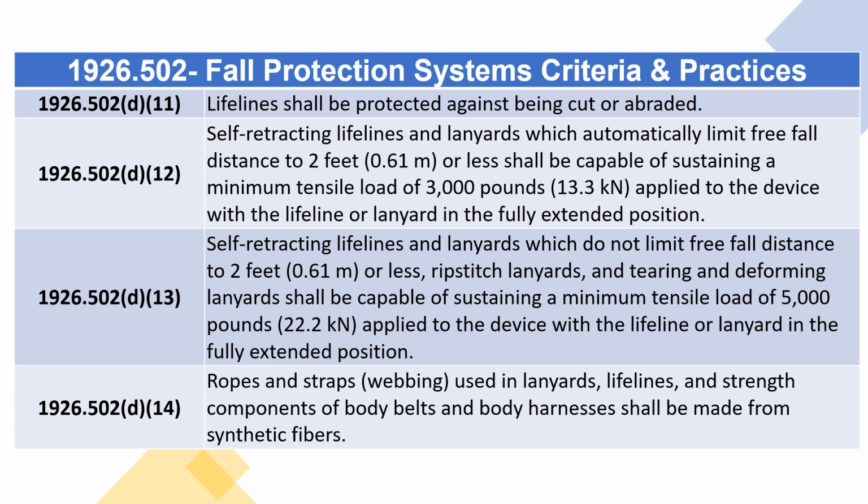1926.502 D12. Self-retracting lifelines and lanyards which automatically limit free fall distance to 2 feet (0.61 meters) or less shall be capable of sustaining a minimum tensile load of 3,000 pounds (13.3 kN), applied to the device with the lifeline or lanyard in the fully extended position.